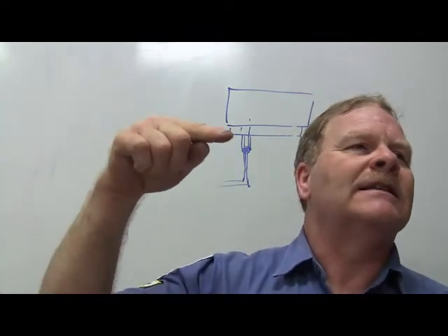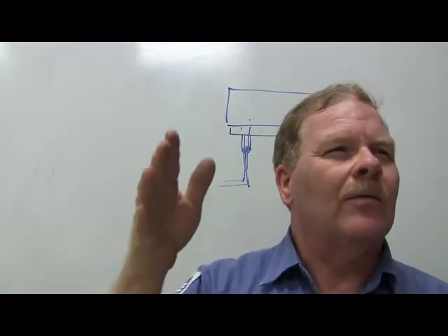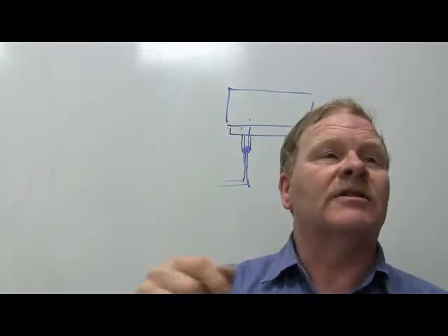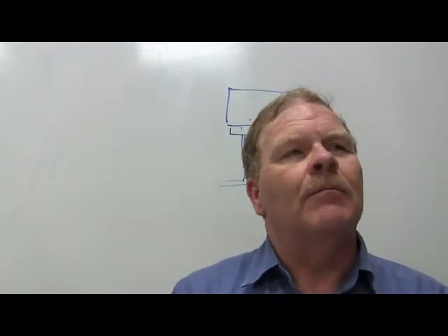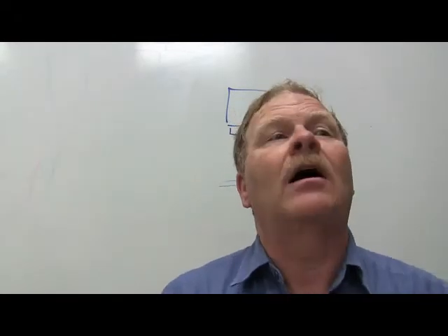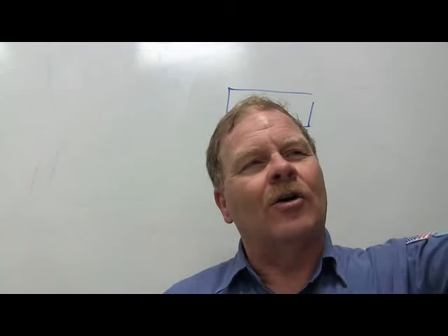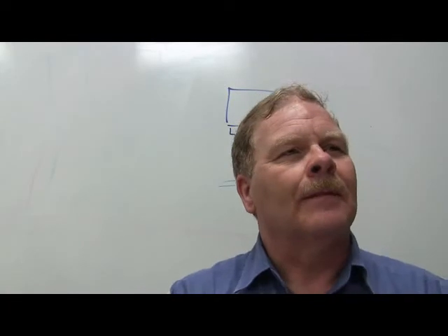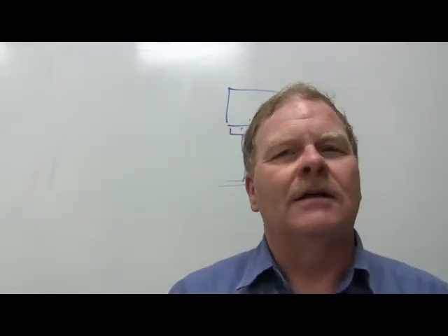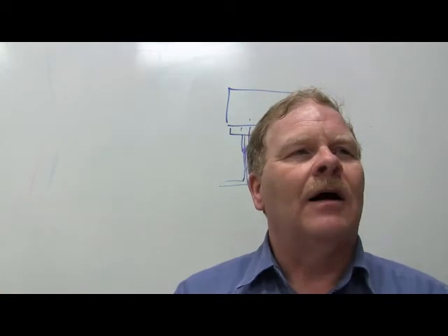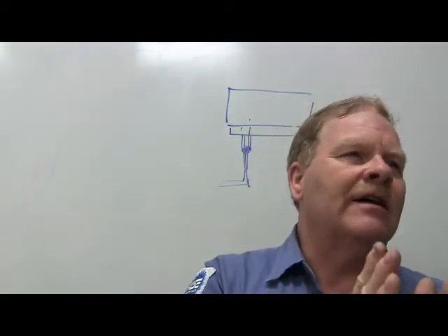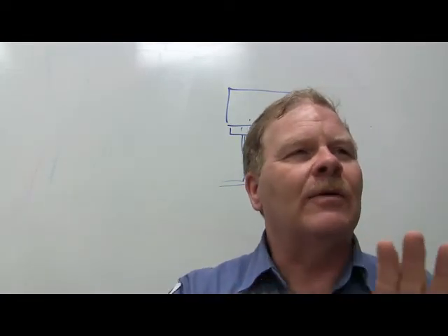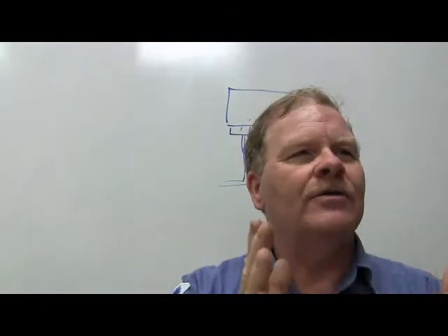But anyway, when the Explorers first came out with that kind of crank sensor in 1991, they had a problem with some of them cutting up and not wanting to start, because in spite of the shielded wire, they had routed the crank sensor wire right next to the negative starter cable for about a foot or something. When you go to spin the thing over and fire it up, all of that current flowing through there was inducing stuff in that wire, and it would cause it not to start. So all we had to do was reroute that wire away from there, so we don't induce anything in that wire.